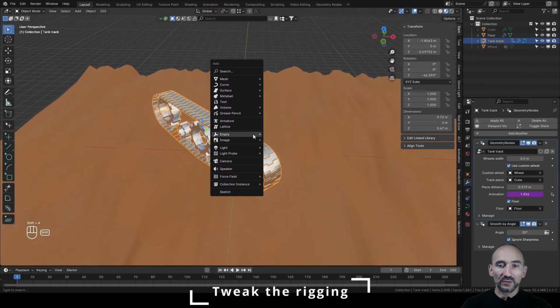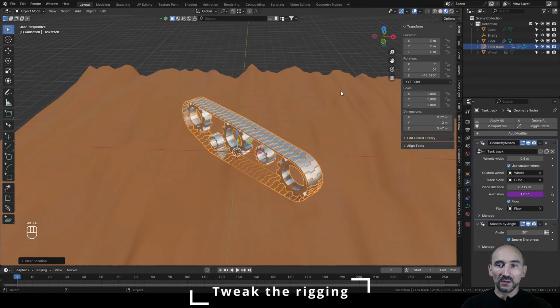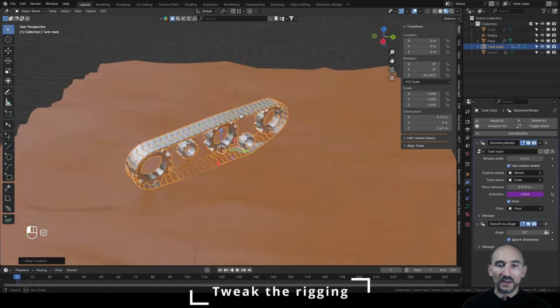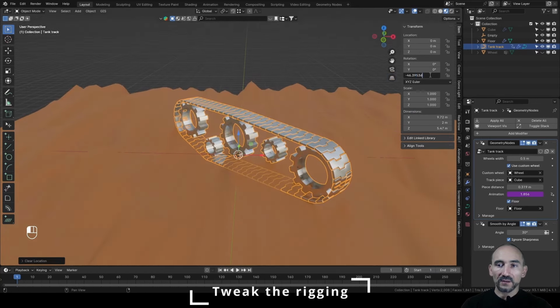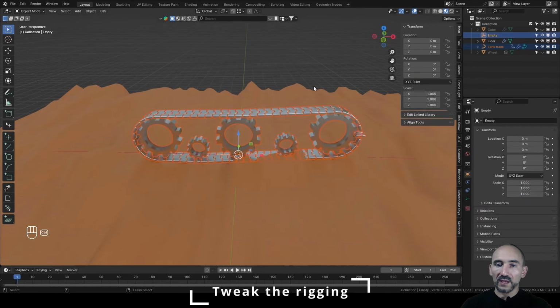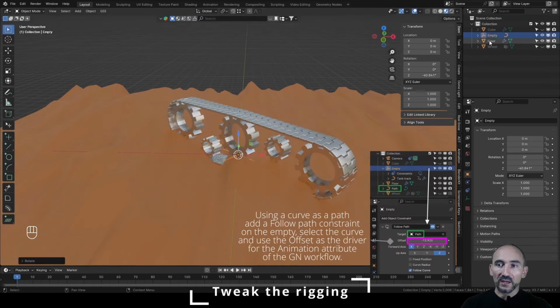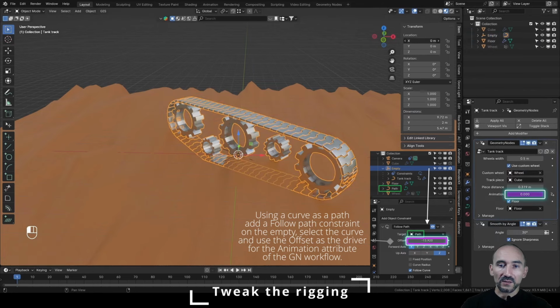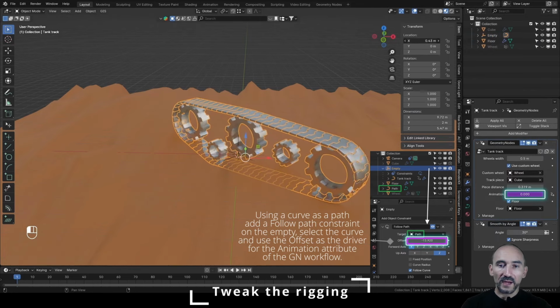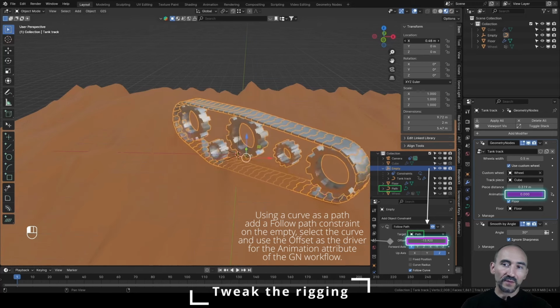So, for example, I create a plane, I reset with Alt and G the translation of my tank track, I reset the rotation here, I select with the control the empty, parent with object, and now if I rotate the empty on the Z axis, I can use the X, the local axis of my tank track, and have the correct behavior of the animation.